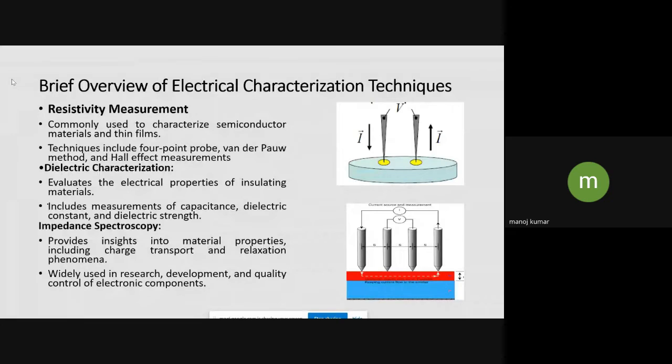After that, there is a solar cell characterization called spectral response. That means measuring the electrical response of a solar cell as a function of incident light wavelength. As all of you know, we are generally focused on the visible range. The visible range lies from 400 nanometer to 800 nanometer. So all the solar cells are planned to use this optical range from 400 to 800 nanometer. This is showing you the spectral response. That means the number of electron hole pairs generated at a certain wavelength and their collection probability.